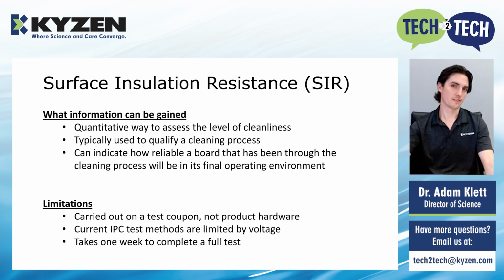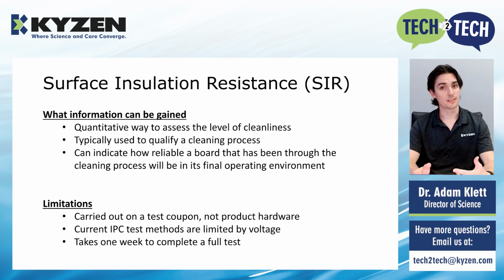So what are the limitations of this method? Well, first, the test is carried out on a test coupon and not on production hardware. However, the test coupons can be designed to be representative of your own production hardware. Also, the IPC test methods don't provide much guidance for testing at high voltages. There's a few caveats that need to be considered before running those tests. And lastly, a full test takes up to 7 days to complete, which limits this to process qualification efforts.